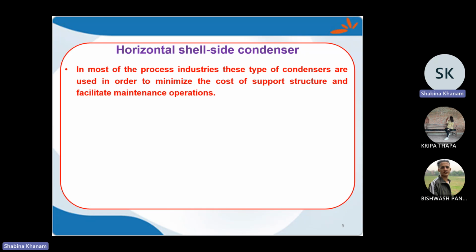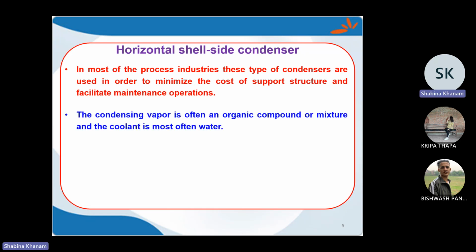And it is easy to place the heat exchanger horizontally and take out the whole bundle for maintenance once it is placed horizontally instead of vertical. You can imagine the difficulty in removing the bundle in vertical position, if the heat duty is large. So horizontal we need to choose when we consider large duty heat exchanger, and when we need to consider shell side condensation.